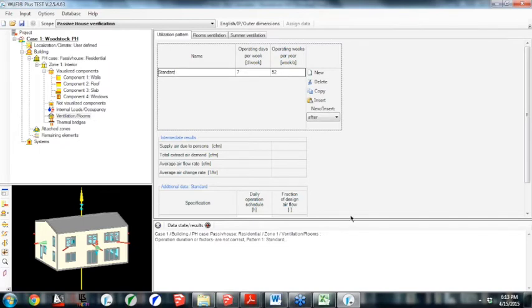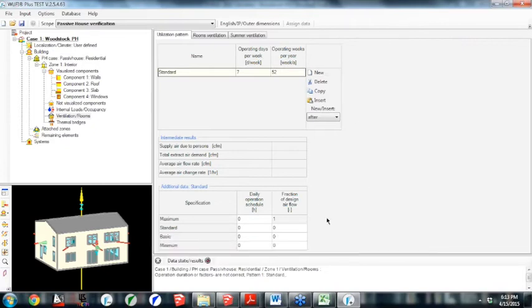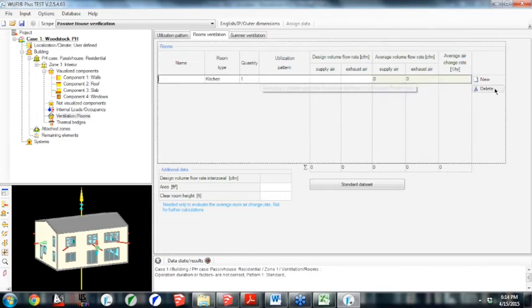Okay, so I'm going to come back to this daily operation schedule. First thing I'm going to do is add all my rooms. So in this list, you add all your exhaust rooms for sure. And I also add supply rooms. I think it's helpful because it sums your CFM and makes sure you've designed a balanced system, but all you actually have to add is the exhaust rooms. Once it knows how much you're exhausting, it assumes you're balancing the system and supplying just as much. But I'm going to add all the rooms.